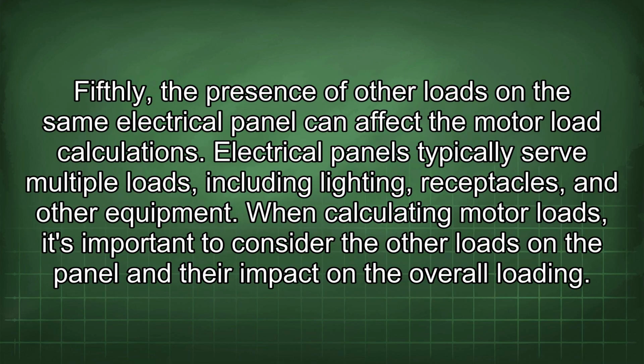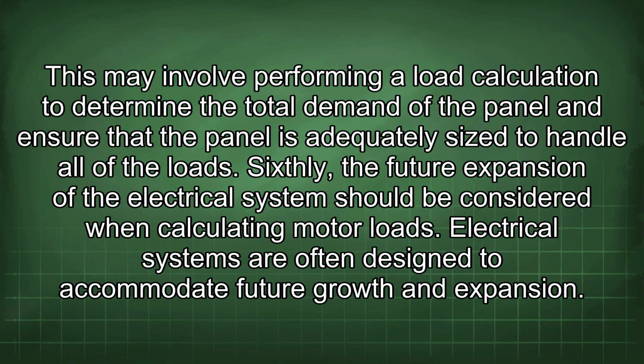Fifthly, the presence of other loads on the same electrical panel can affect the motor load calculations. Electrical panels typically serve multiple loads, including lighting, receptacles, and other equipment. When calculating motor loads, it's important to consider the other loads on the panel and their impact on the overall loading. This may involve performing a load calculation to determine the total demand of the panel and ensure that the panel is adequately sized to handle all of the loads.